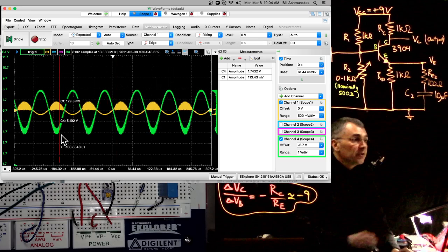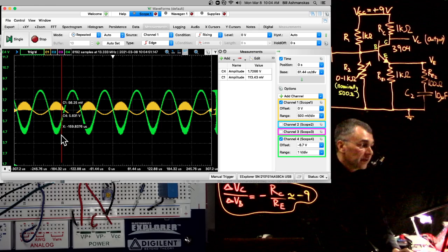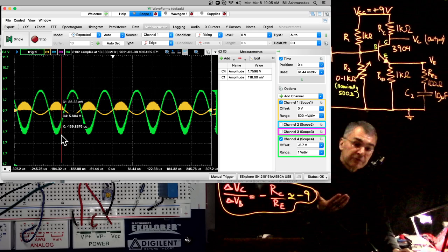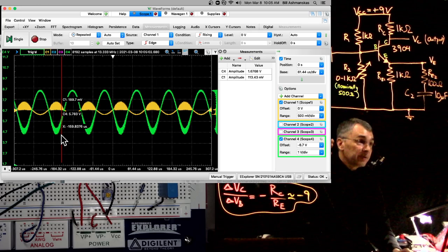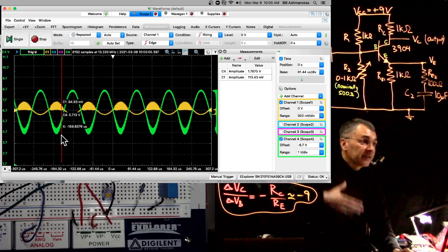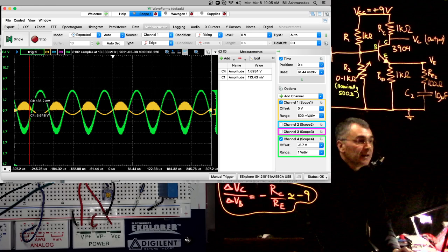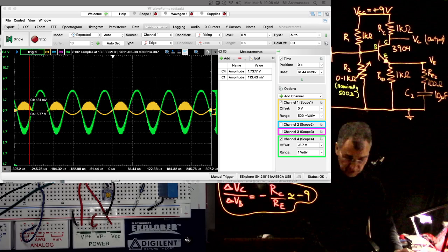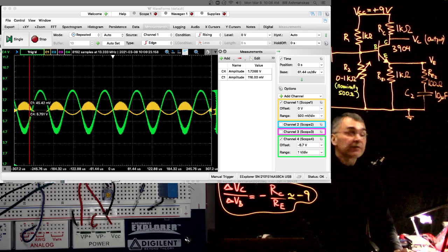Okay, so there are two things I want to do now. One is I want to show you what happens when it stops working, because the transistor cuts off, or because the transistor saturates. Typically you get a limit on the high side and on the low side when that happens. Let me first take a look at the instructions and see what else we were supposed to look at. One instruction that I had skipped was to adjust the potentiometer so the DC voltage at the base is about 2.25 volts. I instead just set it to 500 ohms. So let me do that now.